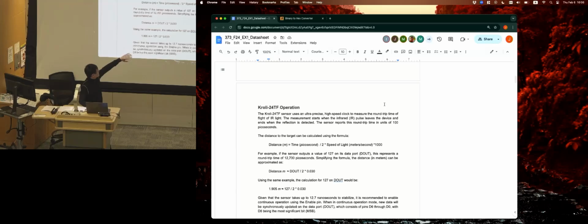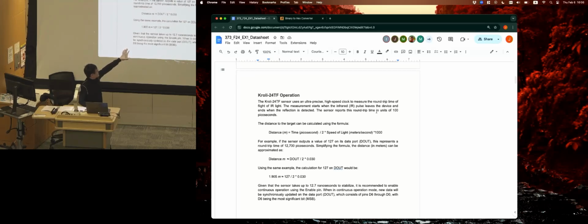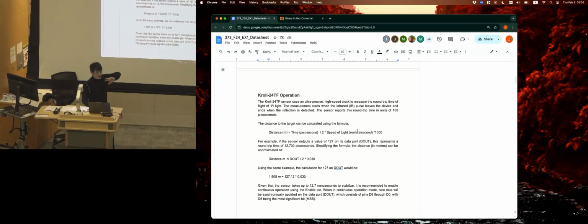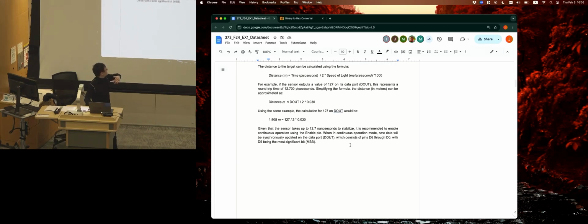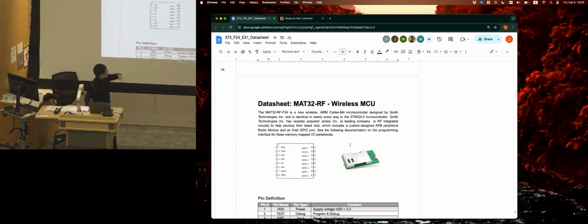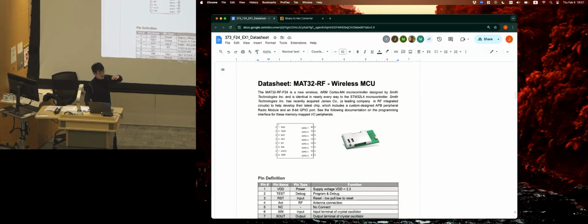And then sometimes, in this case, it tells you how the result is calculated based on the reading of the registers. So this is probably something pretty useful to look at, hopefully before the exam. In this case particularly, it tells you that once it's read the distance sensor time of flight signal, how do we interpolate that signal into an actual number, which is how many meters, what's the distance.